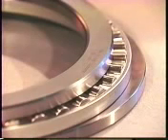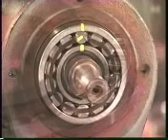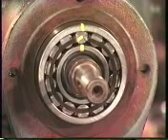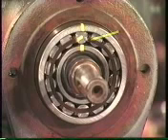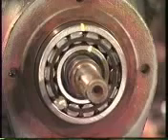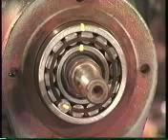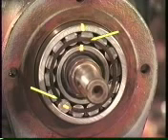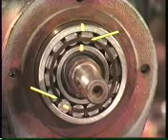Unless the bearing is a unique thrust design with a 90-degree contact angle, the inner race frequency will always be a higher frequency than the outer race frequency. After lining up our reference marks, the cage frequency can also be approximated by rotating the shaft one full turn. With one complete revolution, we see that the cage went less than halfway around. Cage frequencies usually occur between 0.3 and 0.47 times the shaft turning speed.